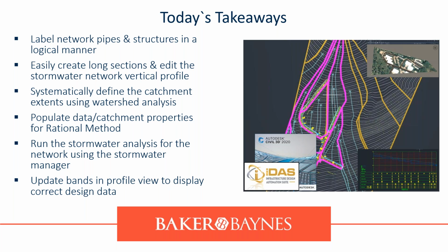Then after all the hard part was done, we simply clicked the button and we ran an analysis. We saw it was a success, and then we said, hey, we still need to check our pipes. We checked the pipes and we saw that we needed to upsize them because they were flooded. So we applied a minimum pipe sizing to them using steady flow hydrodynamic optimization analysis. Once that is done, everything was ticked great. We updated the Manning's to say 0.013 to remove the actual error that was initially there. And then we hit analyze and it was fully successful.